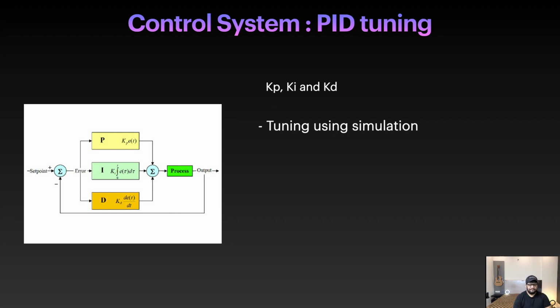You can design a drone in software, and based on your drone parameters, let's say you fix that this is a 2200 kV motor and this is the battery, you can get some values for KP and KD. So you let the computer decide it. But real life is very different, and the best part is tuning by observation. As I mentioned, a small example: if your drone is a bit laggy, when you give a command and it takes significantly more time to execute, then you need to increase the KP and so on. So you tune by observation.